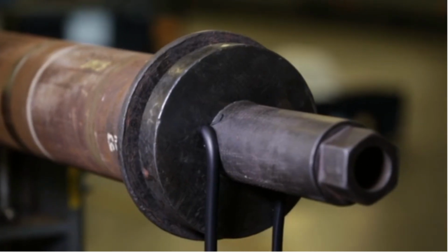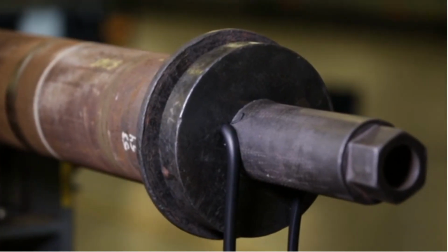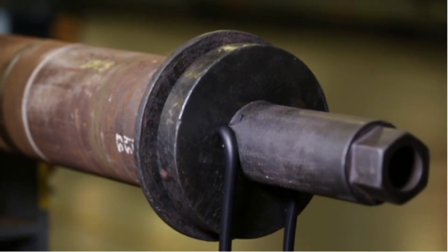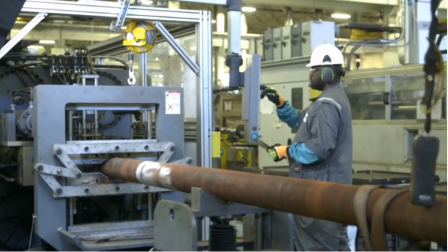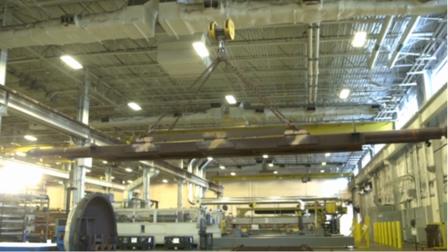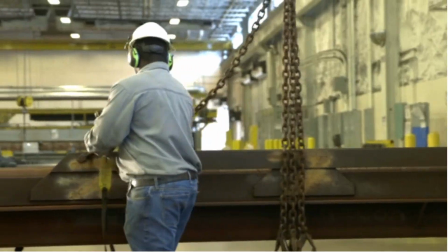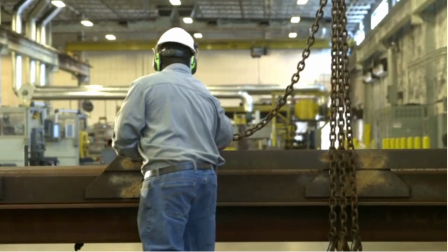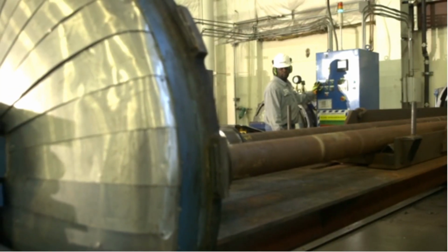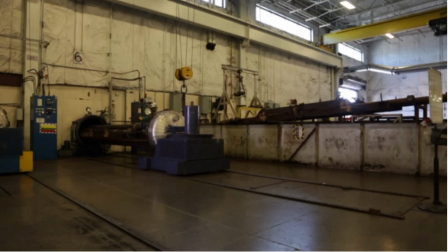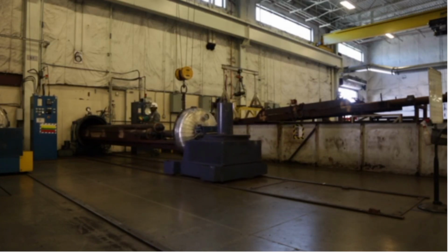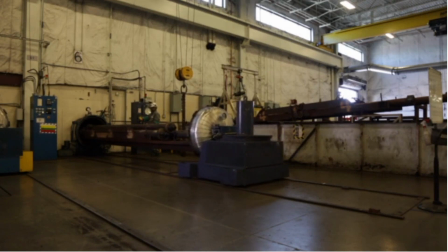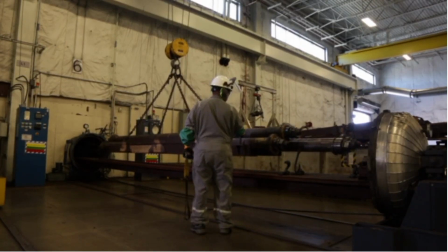The stator is then injected with elastomer, specifically chosen based on drilling application. All injection parameters are set per specification based on the elastomer in use. After injection, the stator is cured with manufacturing precision. Autoclaves deliver precise, CNC-delivered curing cycle times and temperatures tuned to the different elastomers and stator sizes. Curing cycle records are maintained on each and every stator.